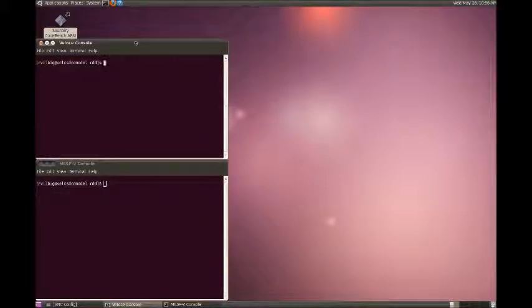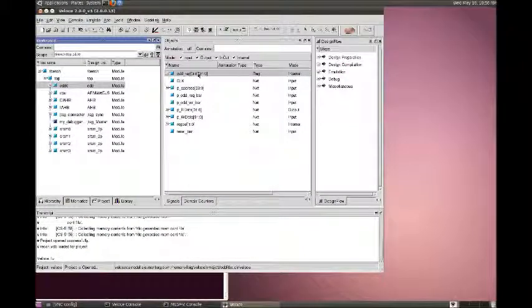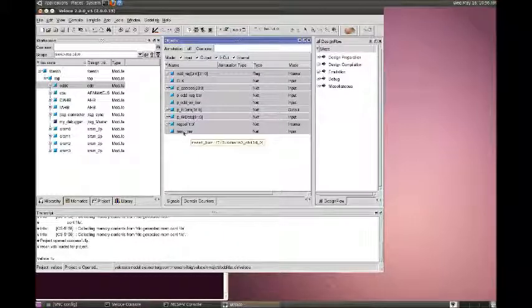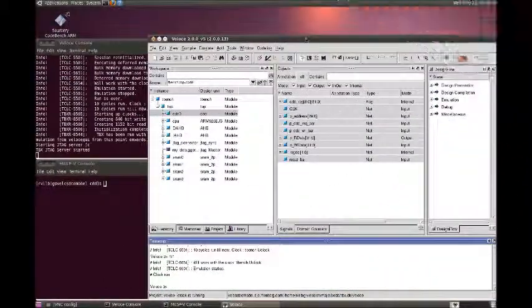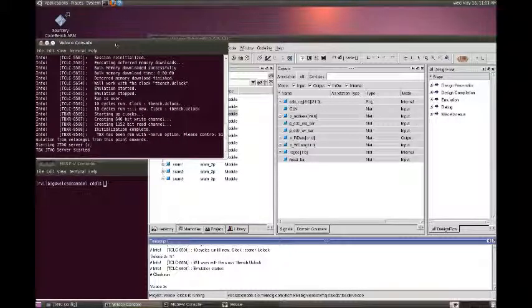The first step is to run the Veloce software, which provides the user interface to the emulator. All of the signals associated with the hardware accelerator are shown here. The next step is to download the emulation model to the Veloce system. The debug port of the processor is exported by the emulation model via a JTAG transactor. When the emulation starts and the JTAG transactor is ready, it starts a server which waits for a debug connection to be established by the virtual probe.